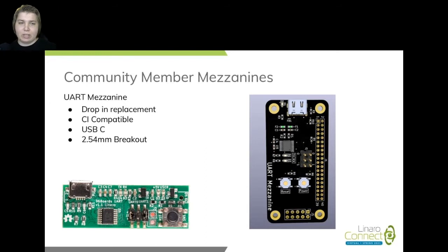It will be CE compatible, features USB Type-C, unlike the micro USB on the old UART Mezzanine, and will also feature a 2.54 or 0.1 inch breakout for GPIOs, I2C, and voltage rails to make it more friendly to get started with some very basic sensors.